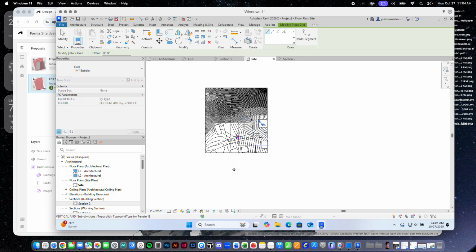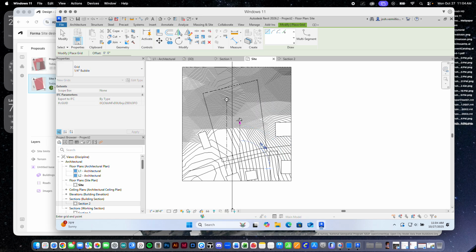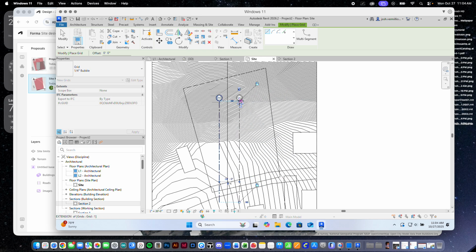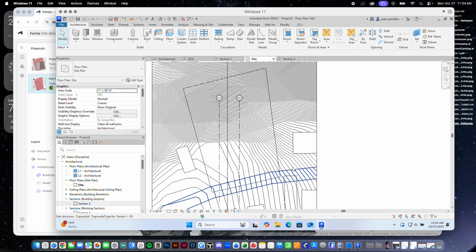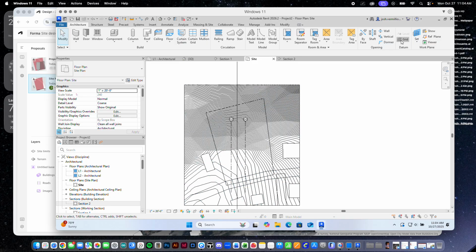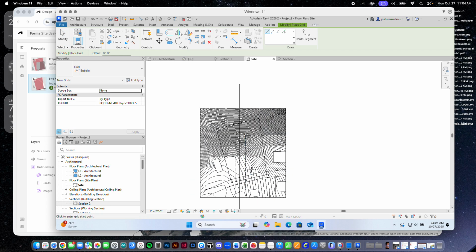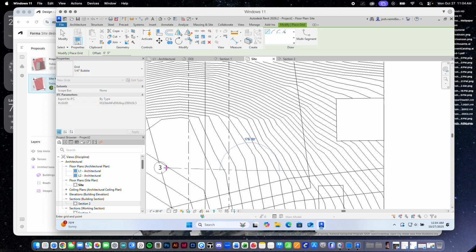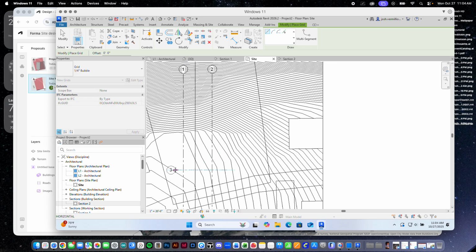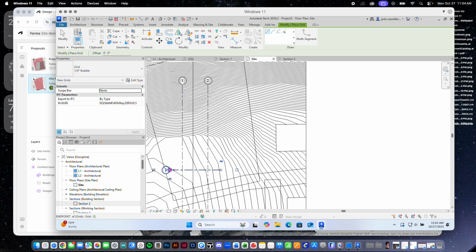As I was going, 32 feet over, so I have a 32-foot spacing between these two columns, right? And then I can go in the other direction, I can do something similar. So I can say, if I want this thing to really face due north, regardless of what the street's doing, I'm gonna go ahead and do this. And let's say I'm gonna do 28 feet in this direction. I'm actually going to put a couple here.